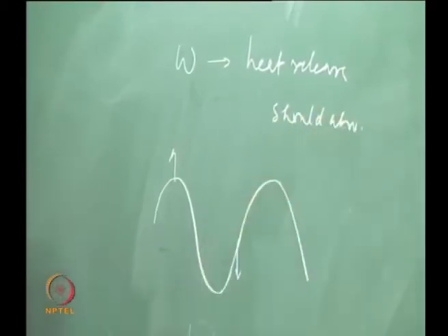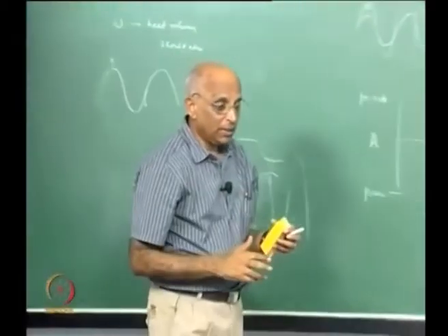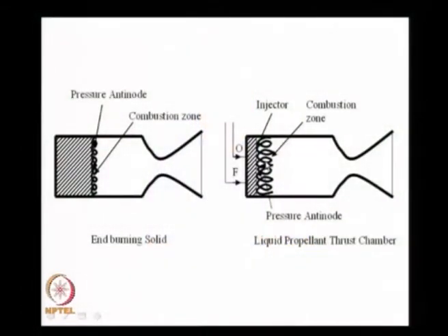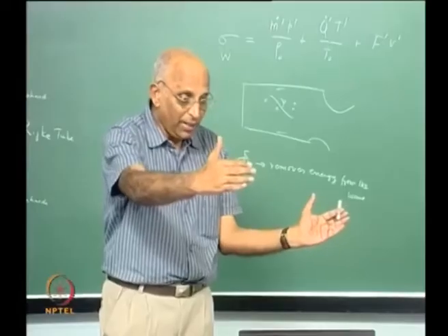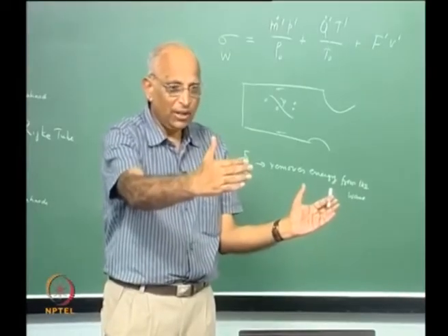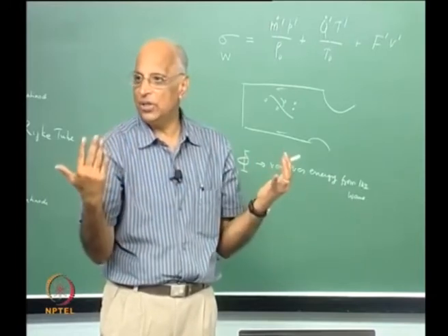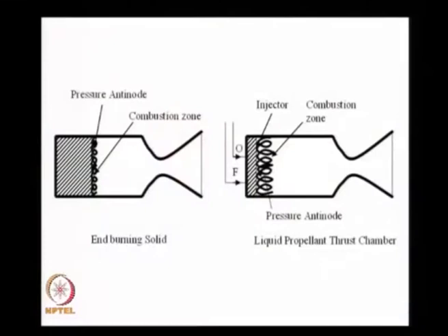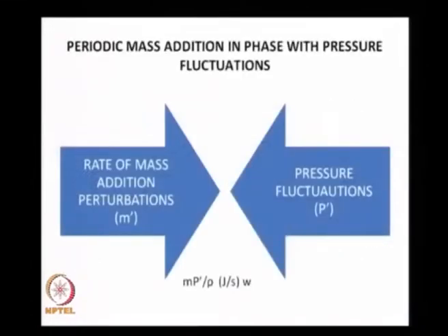And therefore, it is not just a dumb heat release, but the frequency that matters. If I had a slightly shorter Rijke tube, it would have given a much higher frequency. Such high frequency we may not even be able to hear, and that is why I chose this particular length of 1.2 meters or so. Well, this is all what I showed you earlier.